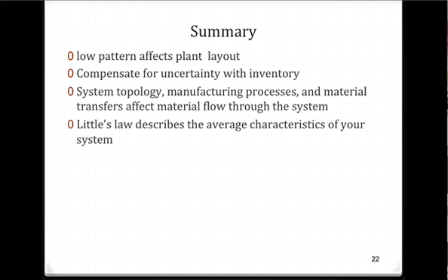Flow patterns affect the plant layout, and that will be based upon your material flow process chart. So you want to pay close attention to how your material is flowing and how that relates to your individual areas of the plant. Obviously, high traffic areas should be close to each other so that you're not transferring material large distances at a high frequency.